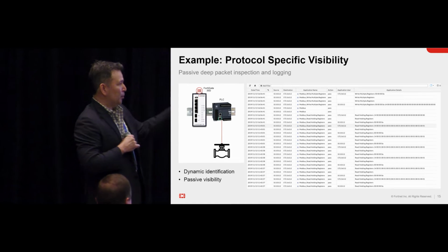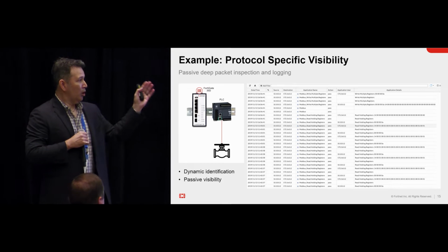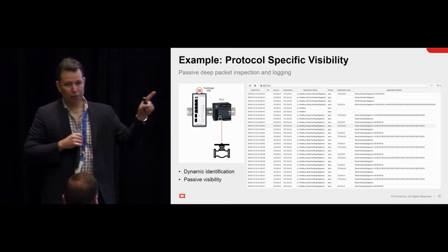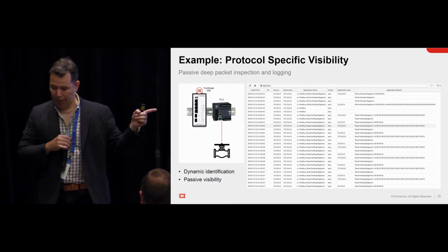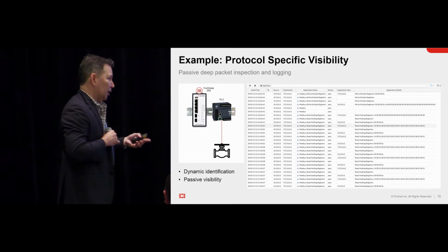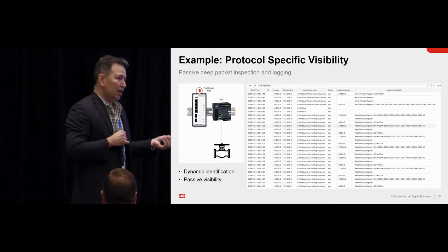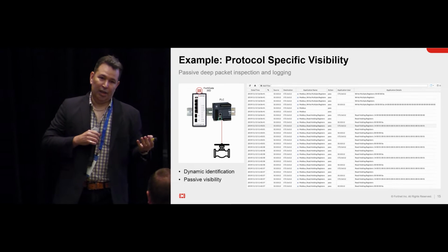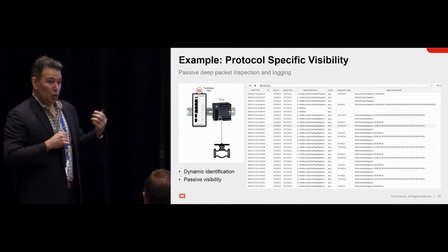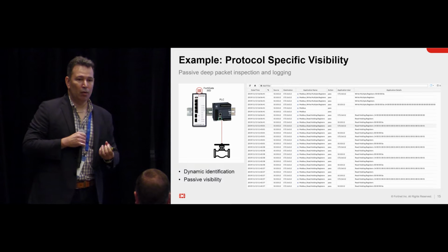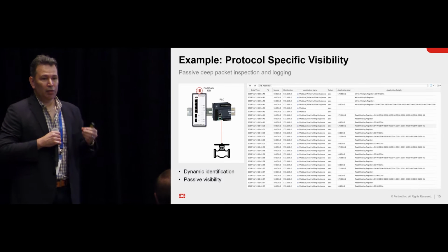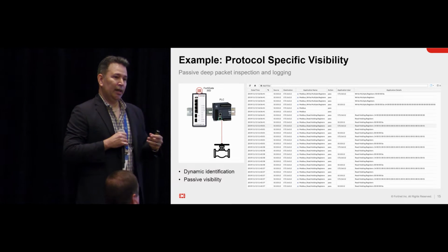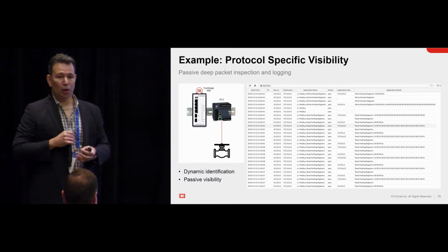If we do deep packet inspection on a Modbus string, we're looking at categories like, what happens if I see that string of 01010101 and then 00A? What does that mean? In the past, there were some CVEs that would take a PLC and send it back to factory default. Well, if you know that is happening in your environment, now you have the power, because you have the visibility, to whitelist your traffic and say, when I see the 0101010100A, then I can say, not only no, but hell no, you're not going across.